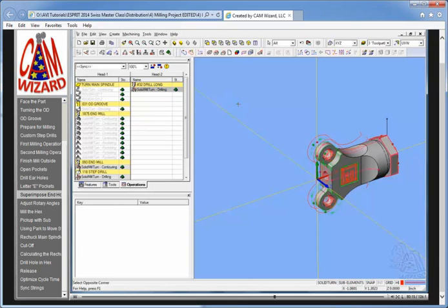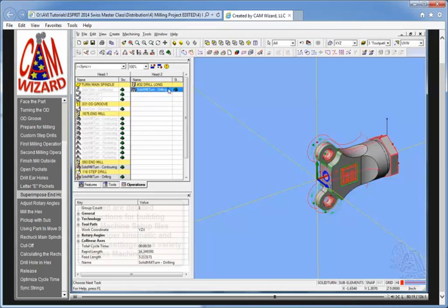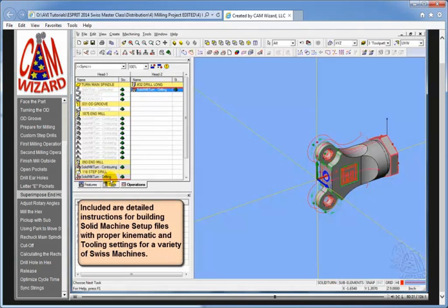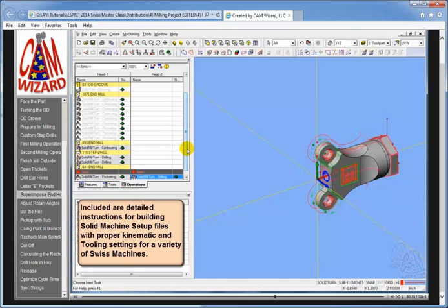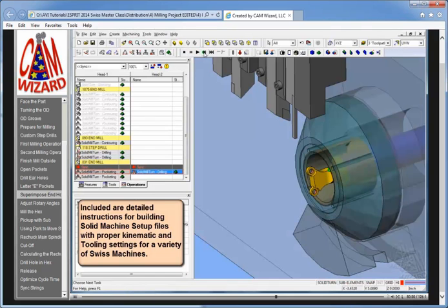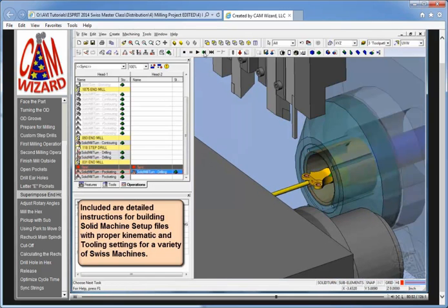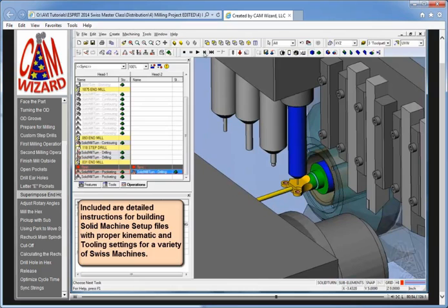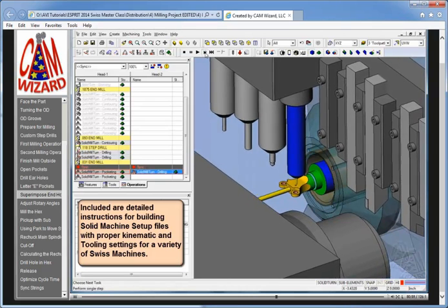Now what we're going to do here is a little different. We're going to take that operation and do it at the same time that we mill the 031 pocket right there. We're going to actually do this pocket and this at the same time. So now notice it's trying to drill, but it's drilling and now trying to mill that pocket.